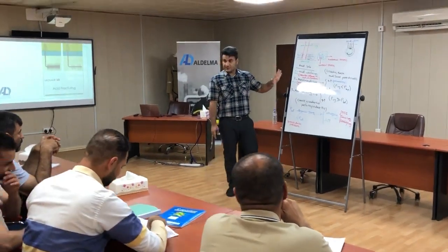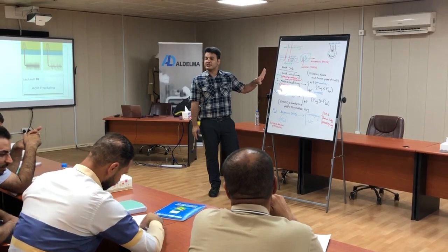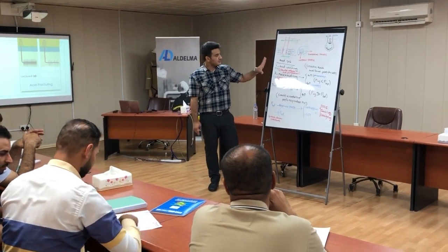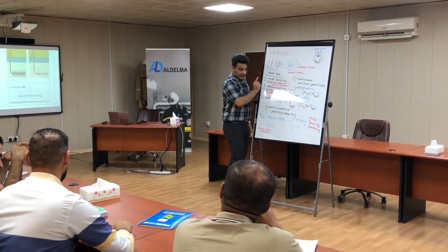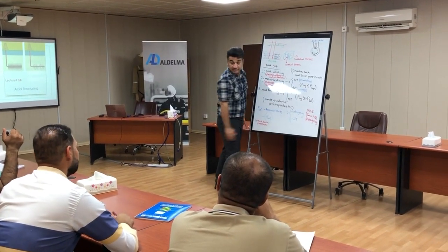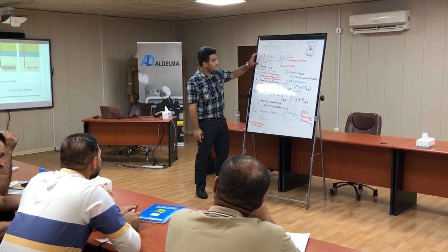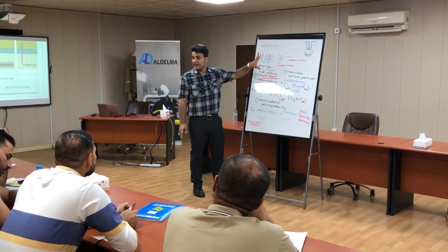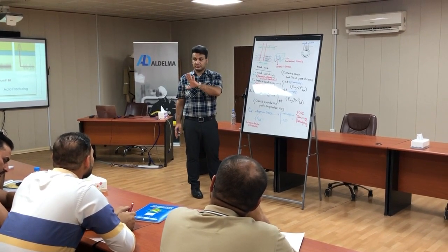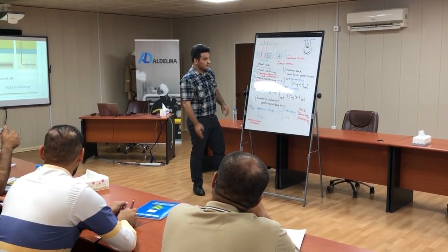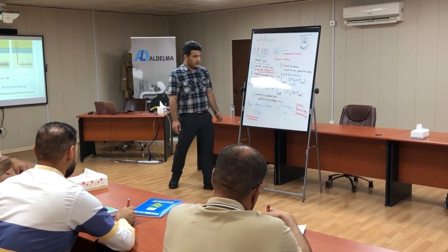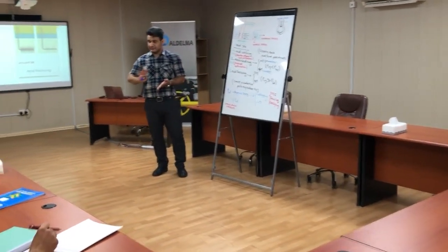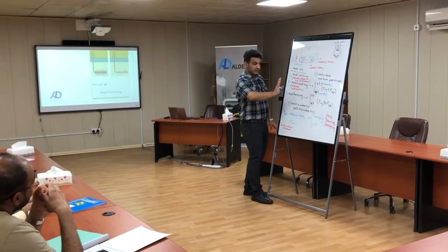The amount of acid is designed by the production engineer. After designing the job, we inject at a pressure below the breakdown pressure to penetrate the acid into the formation. It depends on the amount of the acid. Also, we record the injection pressure. If the injection pressure increases, we stop the job.